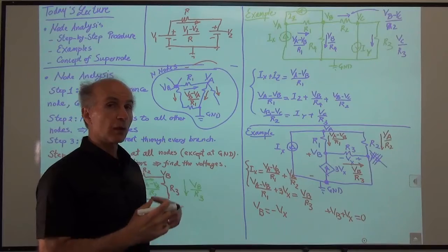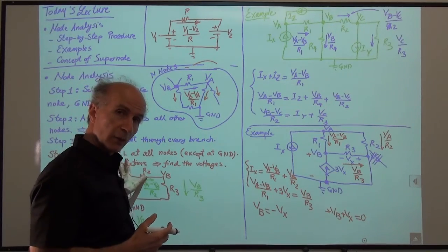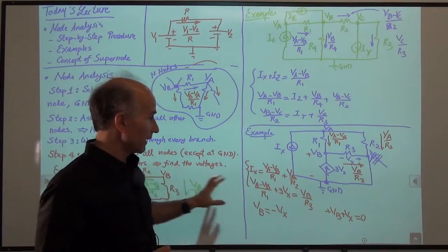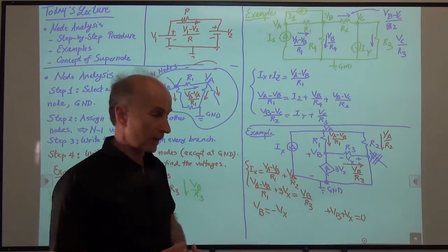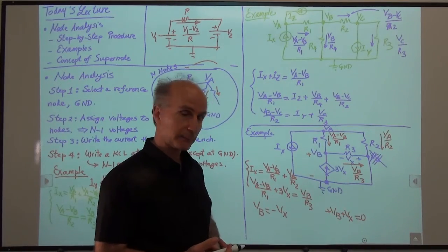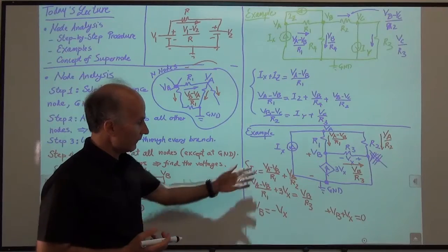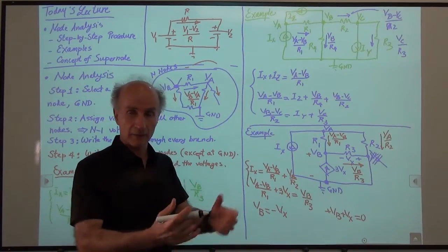Okay, so yes, in addition to writing the node analysis equations, if we don't have enough equations, we have to look for something else, which is a KVL somewhere, because we had this dependence in this particular example. All right, so now that we have three equations and three unknowns, we can find VA, VB, Vx, and everything else.